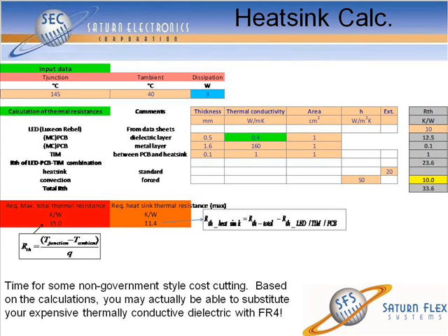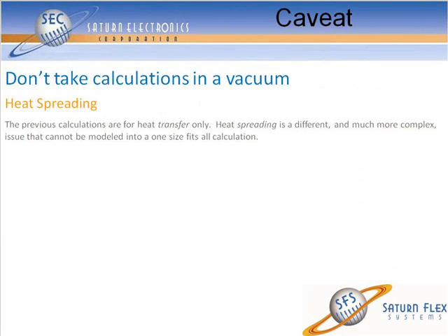So, again, don't take the calculations in a vacuum. Heat spreading has a different dynamic associated with it, but it's worth a try. Again, plug in the thermal conductivity values, see if they work, and then take a look at the heat spreading properties. You're already getting the heat down to your final heat sink. It probably looks worthwhile.